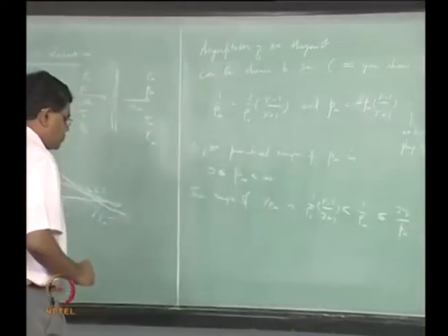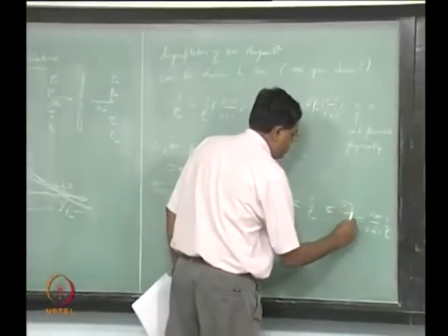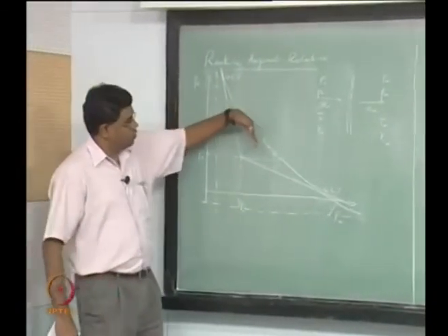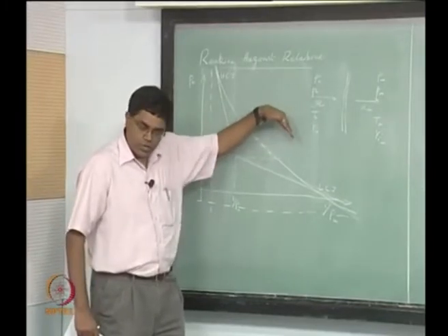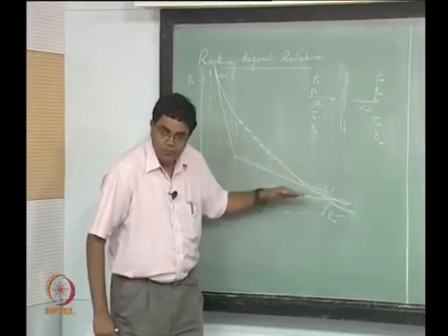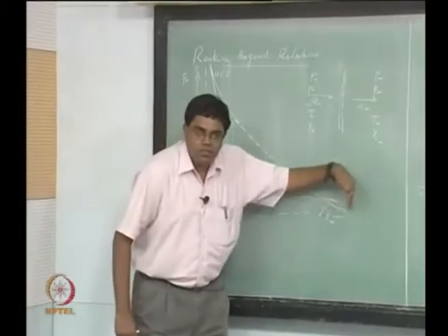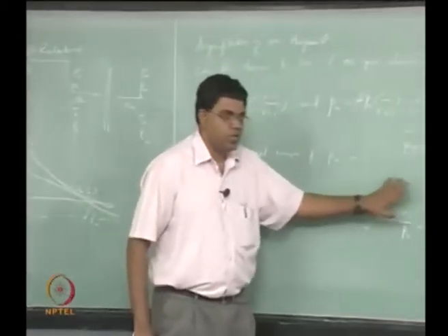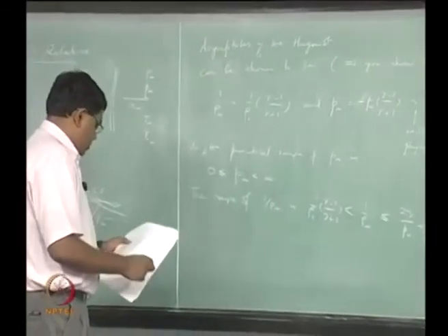Now notice that this is actually dependent on Q. That means if your Q is larger, the Hugoniot shifts to the right and above, and therefore the point where it intersects the p infinity equal to 0 axis shifts further and further out. So as you increase your Q, this term is going to increase linearly. So this is a range.